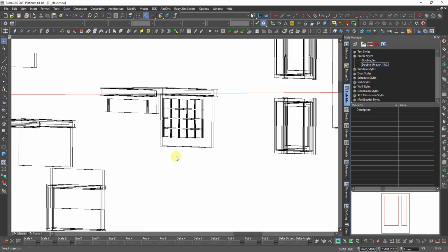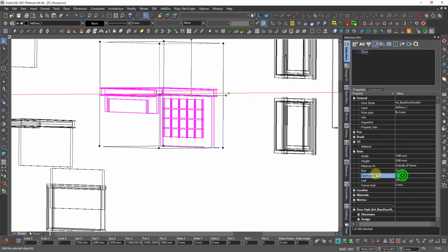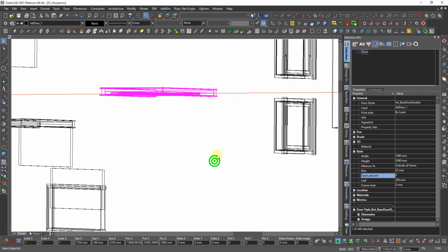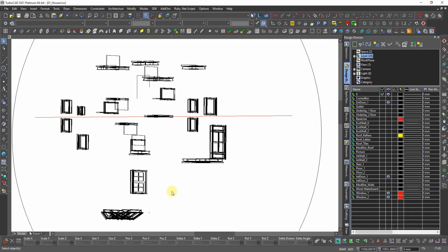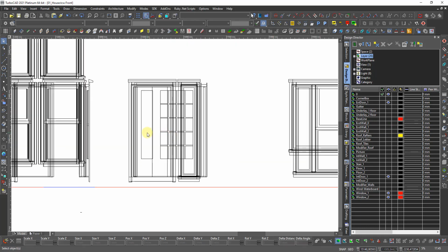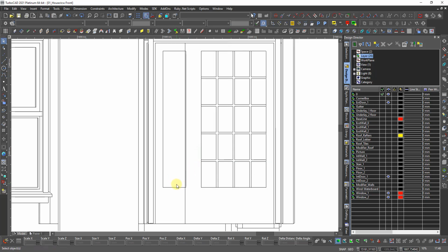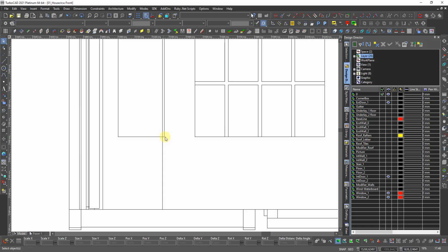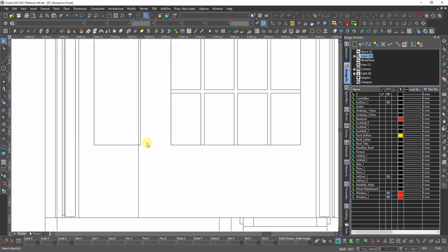There's something wrong in the calculation. If I take that door and I close it, and I don't need the exterior wall, I see it from the front in hidden line. Hidden line. That is the issue. This must be moved 19 centimeter. Yeah, 19, 20. No, how much? 9 do we take? You take 9. That means plus 18 between here, and then we need to take away this distance.